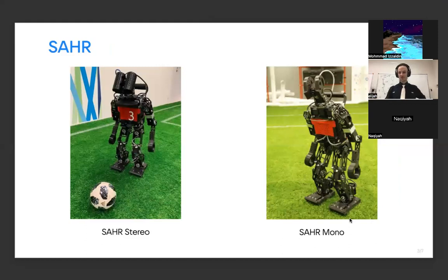So here are 2 versions of this robot that I have shown you in person. It's approximately 7 kilos and approximately 70 centimeters in height. It has 20 degrees of freedom, meaning that it has 3 servo motors per hand, including the elbow. The same symmetrically for the left hand, and in the legs, they have 6 servo motors.